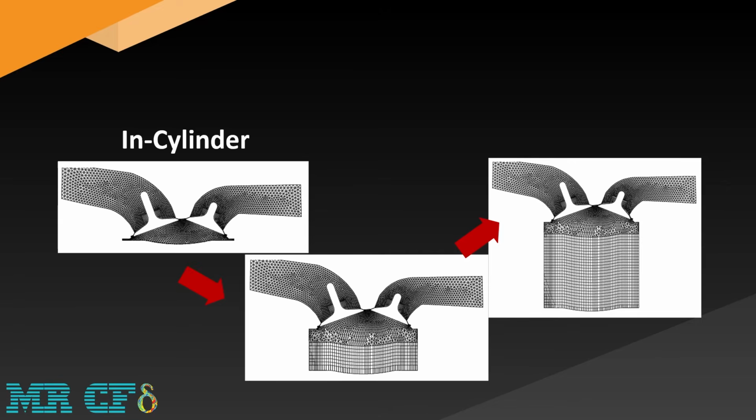To do this, you need to specify the dynamic layering area in the vicinity of the piston surface so that the layered zone moves with the piston to a certain distance from the TDC position. Beyond this specified distance, the motion of the layered zone stops and the piston wall is allowed to continue to reach the BDC location. Since there is relative motion between the piston head surface and the currently stationary dynamic layering region, cell layers are added when the ideal layer height criterion is violated.